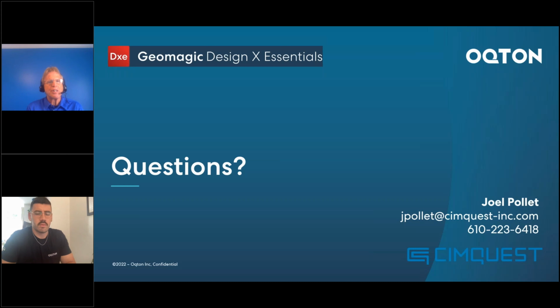That's a good question. When you build a region in the software, if features are specifically cylindrical or planar or conical or spherical, the software will recognize that region as that analytic shape. In the case of the two shapes that I built regions in today, both were freeform shapes, the underside of the airfoil and the top of that very first part we started with.